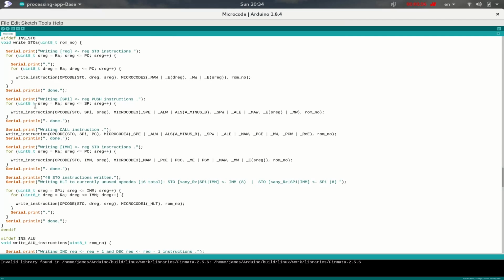And so the microcode for the push instruction here, which is part of the store class instructions, we had a look at that on the CPU just now as well. And so that too is a 3-step operation. After fetching the instruction, we need to actually decrease the value of the stack pointer, because it's currently pointing at the lowermost full cell of the stack, and so we want to write something into the cell underneath that.